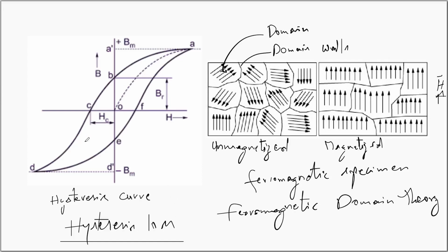If the area under the hysteresis loop is small, then smaller will be the hysteresis losses. Similarly, when the area under the hysteresis loop is large, higher will be the hysteresis losses. Based on the area under the hysteresis loops, the magnetic materials are classified into two. They are soft and hard magnetic materials.